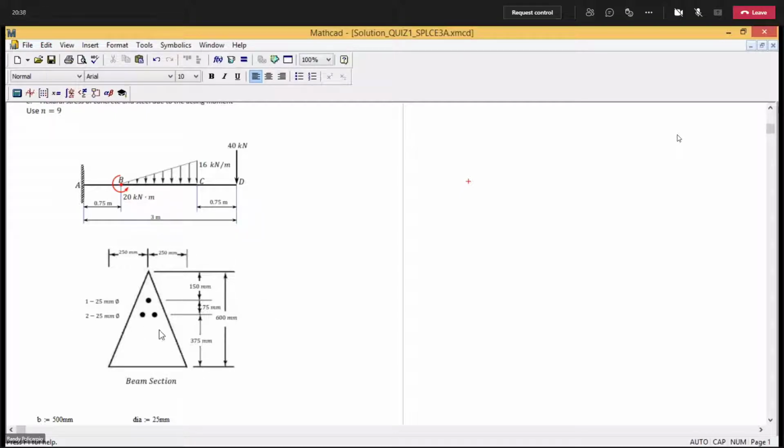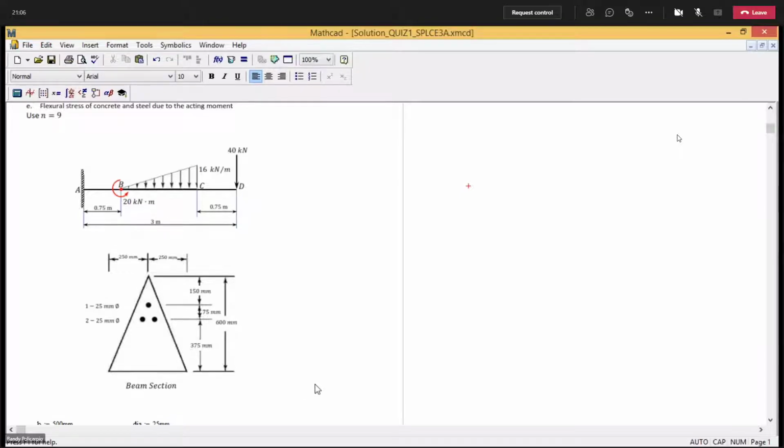So top above the neutral axis will be under tension. So the reinforcement here will resist yung tension doon sa ating beam, while at the bottom is under compression. So we're looking for the location of our neutral axis with respect to this bottom. Okay, so kailangan ganun mo siya kunin, ha?